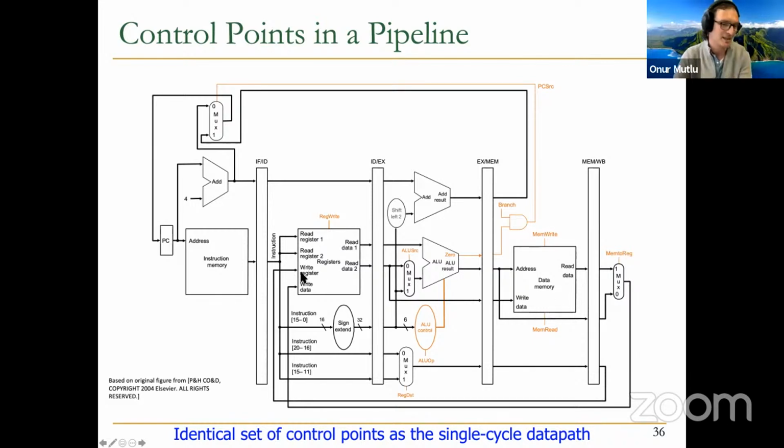And I'm omitting some things also. PC source muxes over here. There are actually real muxes over here. This is a simpler version of the processor that you have seen. But essentially, the takeaway is control points are the same. But when you exercise the control is different. Meaning, you need to be careful when you set the reg-write signal.